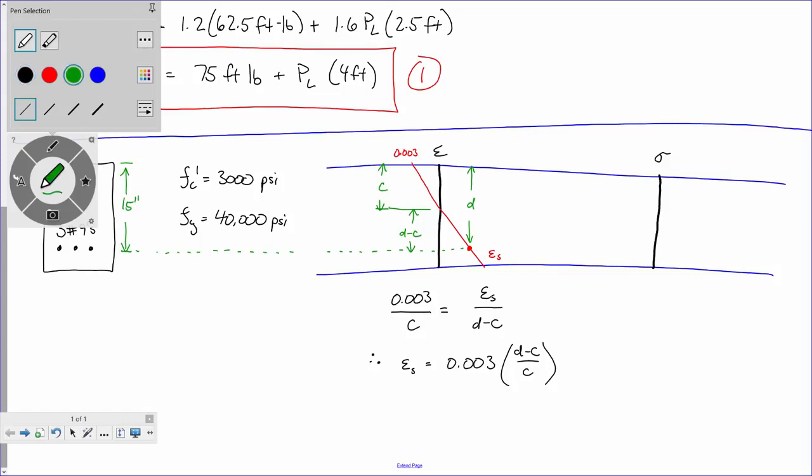If I take this neutral axis line and extend it, I see no effect from the concrete below. The only force that I see on the bottom is this tensile force, which for singly reinforced beams, I can assume has yielded, because the strain in the steel has to be greater than 0.004, so it has to yield.